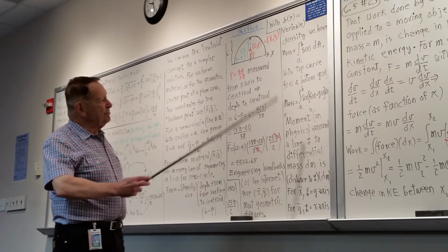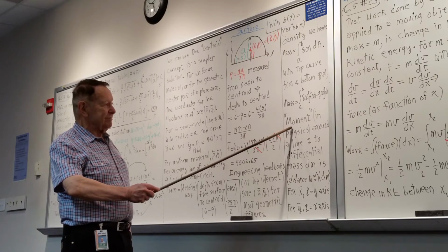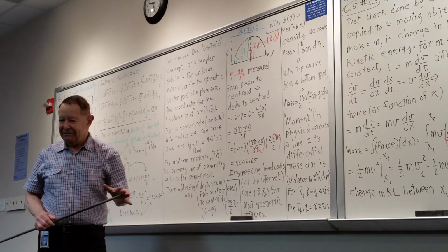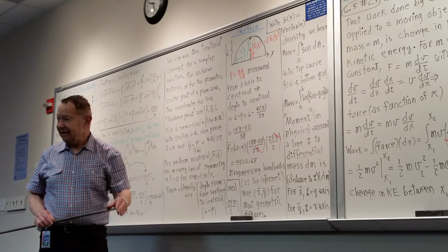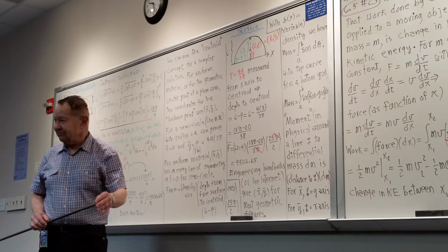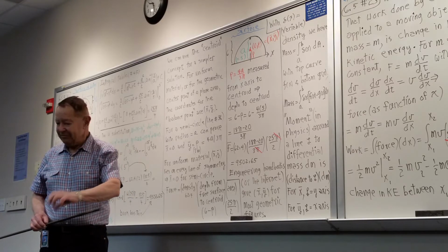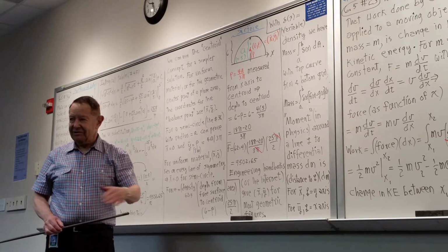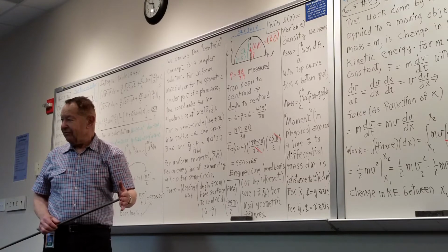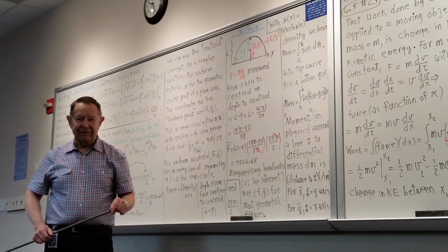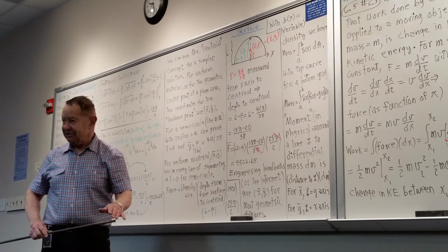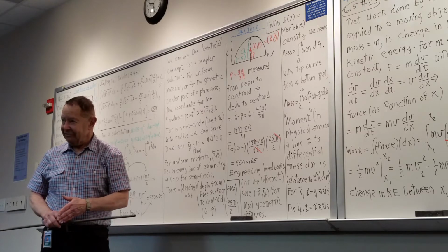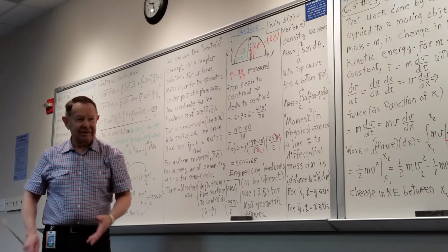Okay, so what we call the moment in physics is like torque. It's a leverage length times the force, which is also what, say, if you have a wrench, you put the wrench on some fitting and you're trying to turn the bolt, what the force that is available to you is what you call torque, which is the length of the wrench times the force at right angles to the wrench handle.